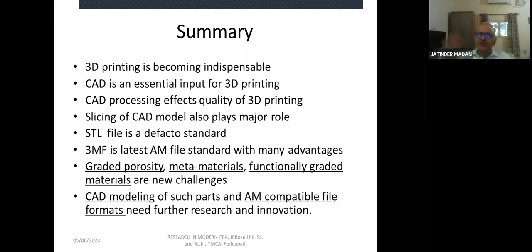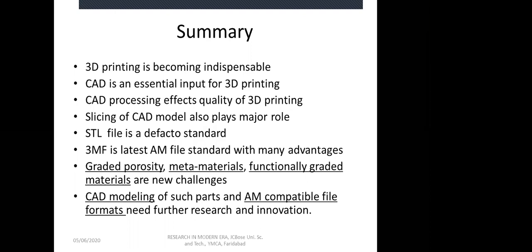The only thing is you will have to choose whether you want standard printing, high quality or speed, and you want to manage other things, right? How to build it, that you can manage, like I told you, whether you want to keep it horizontally or vertically. So those things you need to manage. Okay, but it is pretty easy. The only input required is the STL file, so you can take that as a print.